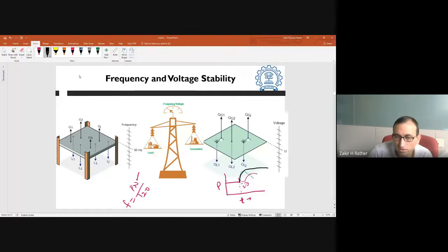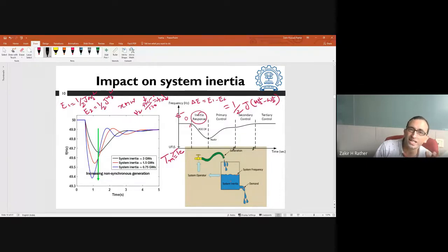And of course, depending on where your governor settles down after this disturbance, you will have the power output here accordingly. And the inertial response will settle back down. So the inertial response is very fast, but it is for a shorter duration. It is this inertia which has been saving the conventional system, because it makes sure that there is instantaneous balance between generation and load in the grid at each and every instant. There is no technology in the world that can bring additional generation as fast as this inertial response.